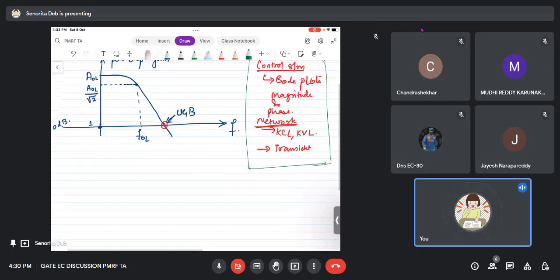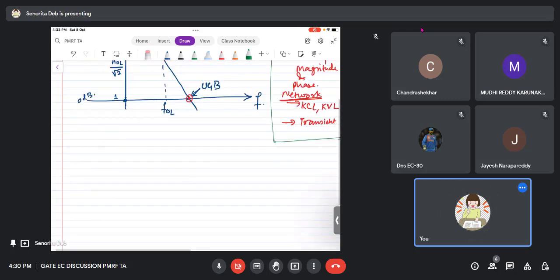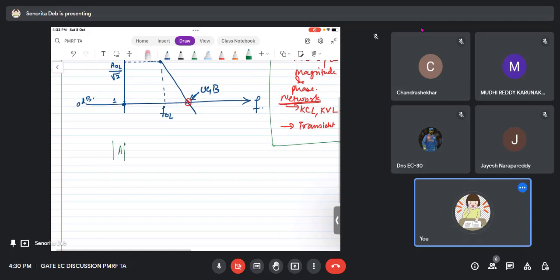Okay, the closed loop gain, so the gain at other frequencies, is calculated with this formula. I'm not going into the derivation and all those things. It is 1 plus F by FOL whole square under root, and you will see that it matches the one that low pass filters normally have.